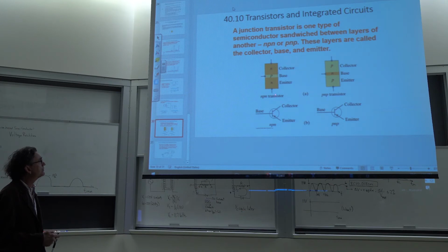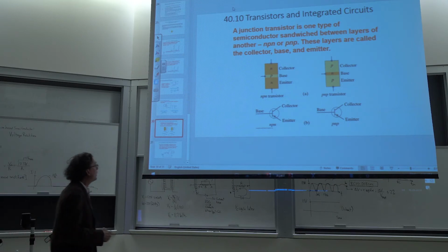It turns out that oftentimes, even though this potential up here is higher than the potential at the positive pole carrier, if this region right here is thin enough, and if this voltage between PN is large enough in the forward bias case, with positive voltage on the P side and negative voltage on the N side, the conduction from the top will also be very large.